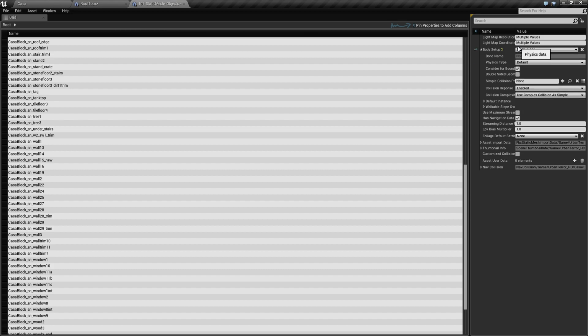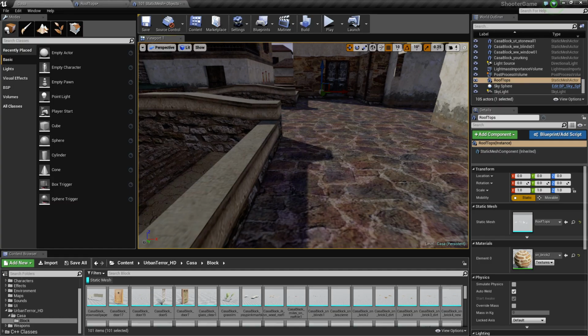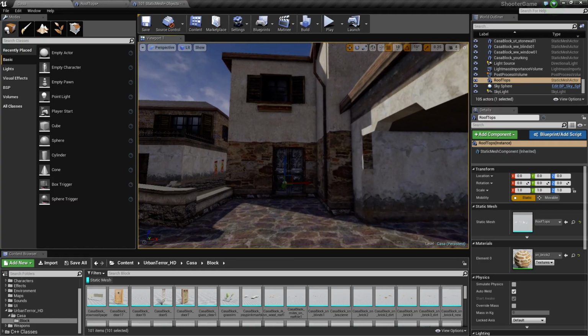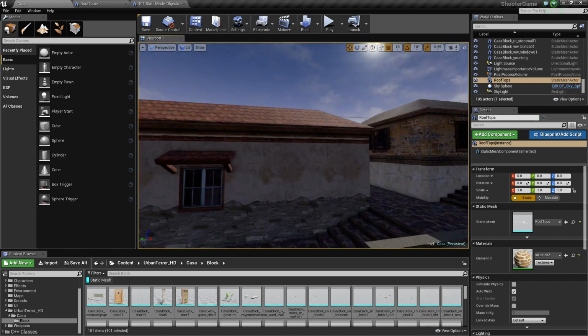Light map resolutions, you can also change, as well as what channel the light map is located on. If you use the self-generated import, that would place your light map on channel 1, but you can have different light channels if you wish. If you want to make your own, you can place it on, say, channel 2 or whatever. So it's completely flexible in that way.